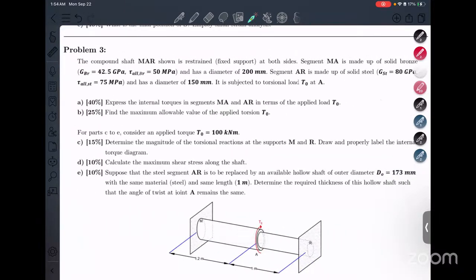So for this shaft, what you want to check is which one is the weaker one, quote unquote. Alin yung una bibigay. So we will get two individual maximum P naughts, and then the smaller one becomes the allowable value for the whole shaft, right? Because if we reach the smaller value, then bibigay na yung weaker subshaft, or section of the shaft. We have to use the smaller value.